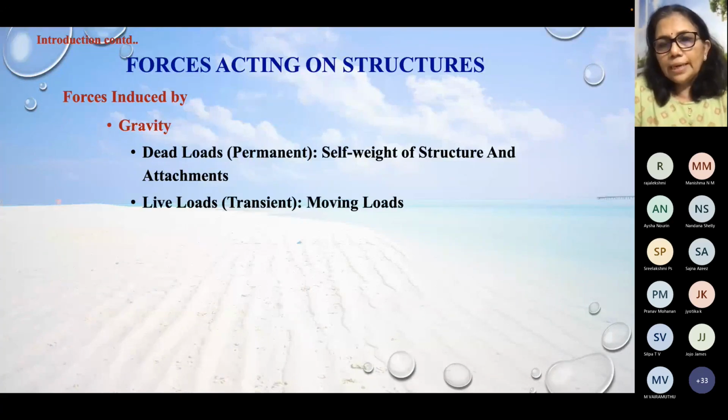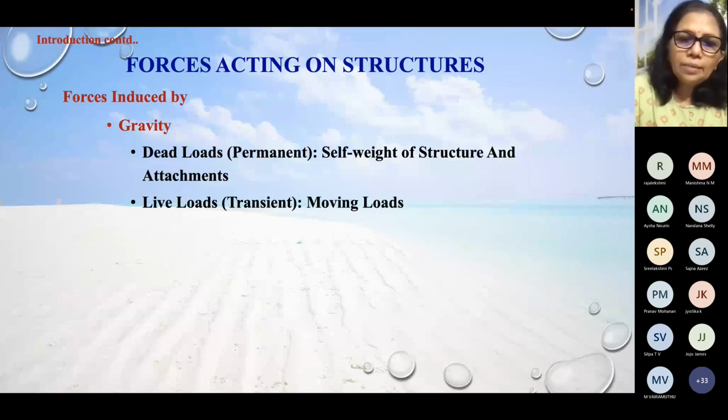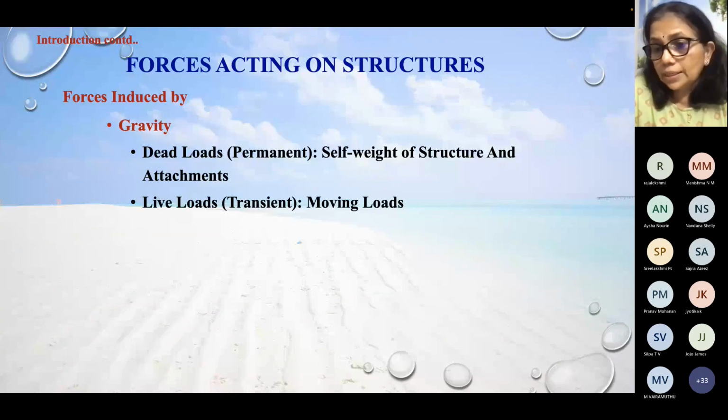Like if you are designing an educational building, the furniture, the desk and bench, will be permanent in nature in the classroom. So it can be considered as a dead load. And there will be live loads, which are also called imposed loads. And there will be moving loads. You might have studied moving loads in structural analysis.